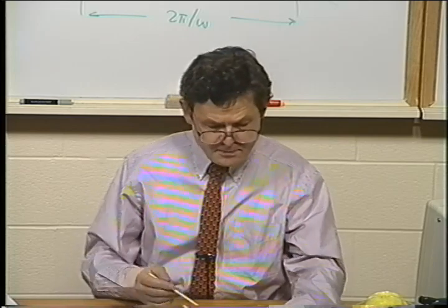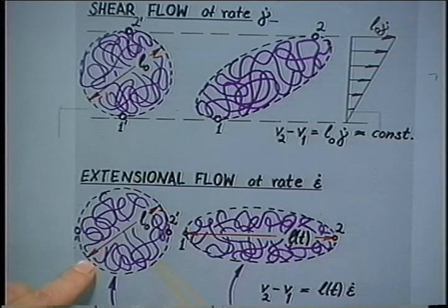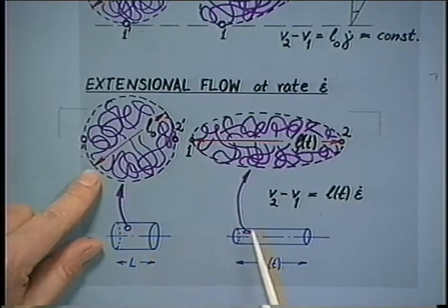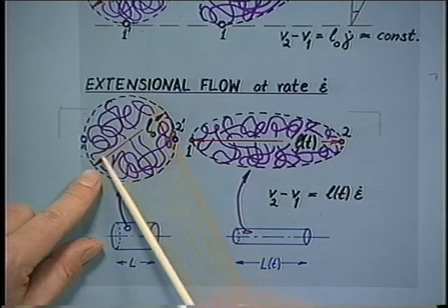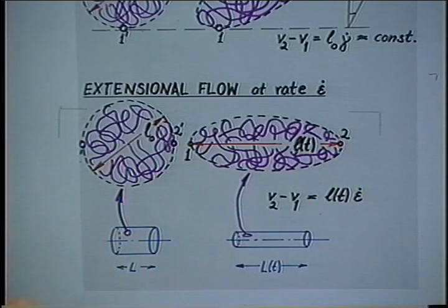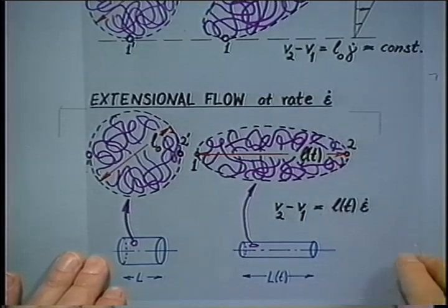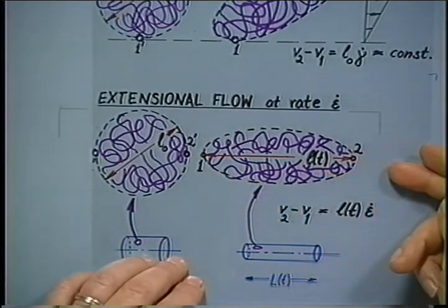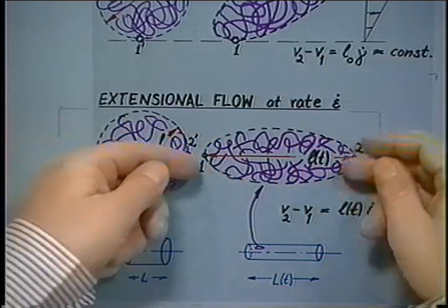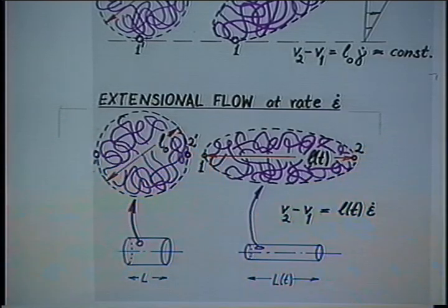It gives rise to some interesting phenomena. Now, quite normal in extensional flow. Let's say a molecule is part of a little piece of rubber which is being stretched here in this deformation. Then this molecule will be elongated, and it wants to retract also and gives rise to a stress, because it's ordered here and disordered in the relaxed state, an entropic stress contribution, which we're talking about. And that's quite normal. That's used in fiber spinning. You can spin fibers out of polymeric materials because they are supporting a stress of this type. It's a very nice property of a material.